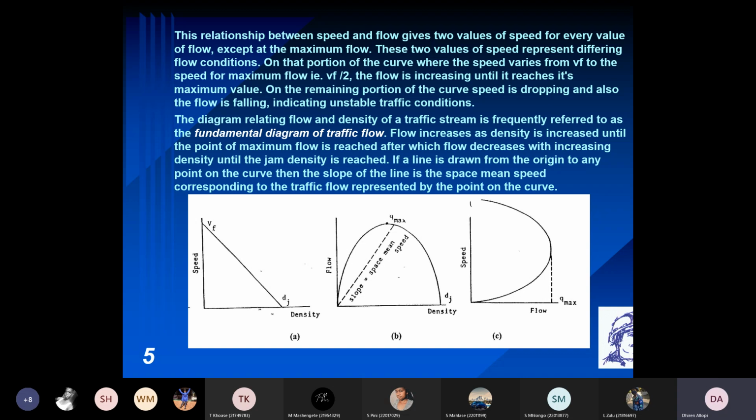So if I then look at the flow density relationship, you can see, as I said, because you've looked at the equation, V squared in your equation. You can see from the graph, once again, at that point where you have zero flow, that means there's no movement, all your vehicles are queuing. That's when you would have the maximum vehicles in a queue, which we refer to as your jam density. So there's your jam density at that point.